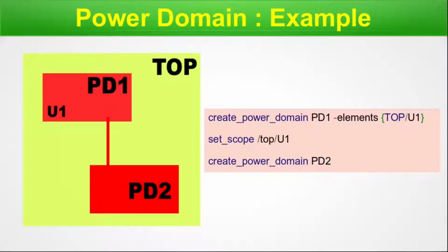Next, we use create power domain PD2. Now, as we create the power domain PD2, it automatically comes under the scope that we have set just the line before. So this is how you can create a hierarchical power domain. Okay. That's all for this particular slide. Let's move on to the next slide.